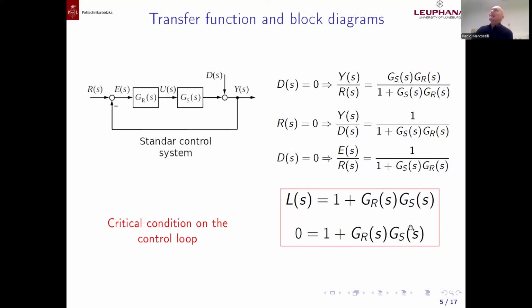We can understand, as I told you when I introduced the Laplace transformation, that if you have poles with positive real part, we have an unstable behavior. At that time I didn't tell you about instability, but the inverse transformation is a function in time which goes to infinity.